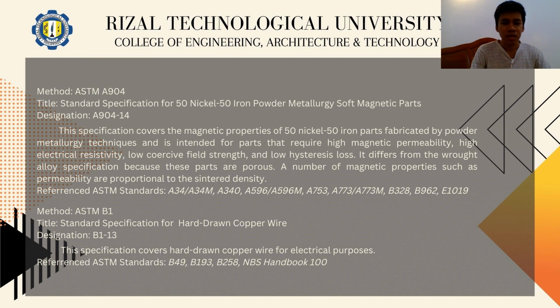It differs from the wrought alloy specification because these parts are porous. A number of magnetic properties such as permeability are proportional to the sintered density. Magnetic parts shall be tested and adhere to chemical composition and sintered density requirements, on which magnetic and residual induction strongly depend. Parts shall also be tested for their conformance to coercive field strength requirements.